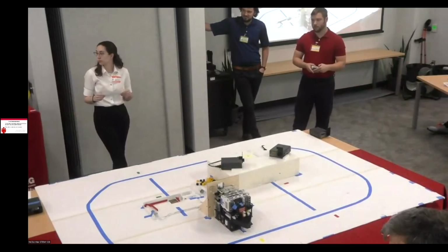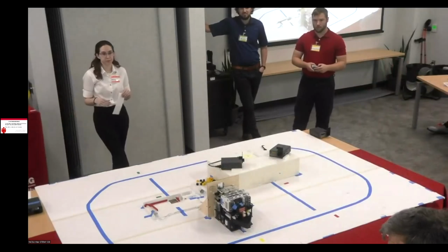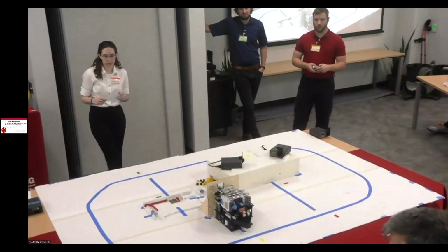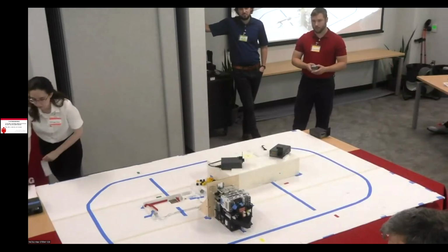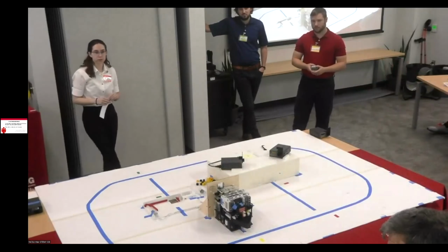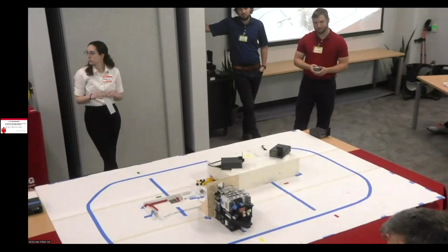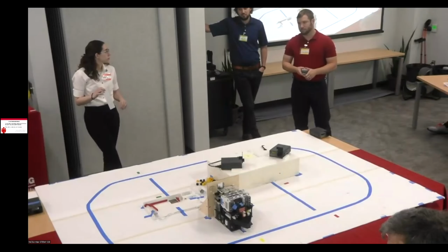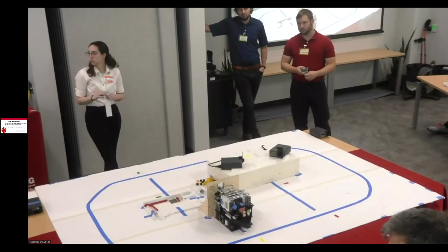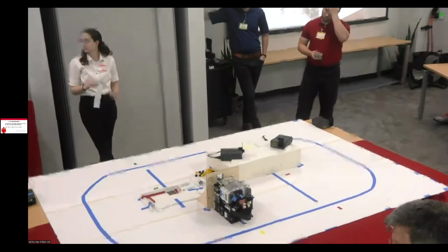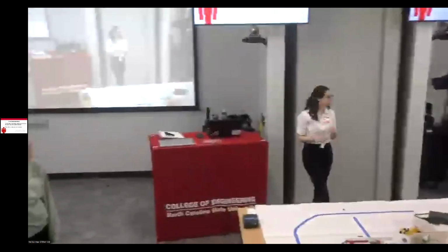That was after critical design review. After integration, right? Yes, once we had put everything on and we had the weight distribution like it is right now. We had done a test with more weight than what we were anticipating the entire AGV to be sitting on the center, so all that weight was over those drive wheels, and it didn't have the issue popping up over the dowel rod with those hard wheels.